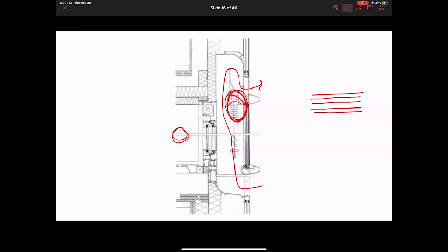And they're really beautiful. They're amazing wood screens, but every photo I've ever seen of these is taken right when the building's completed. With one exception, I've seen a Herzog and de Meuron building with one of these that's 20, 30 years old, and they sag. They're really thin horizontal wood in wet climates often, so they warp and twist and split and rot and sag.